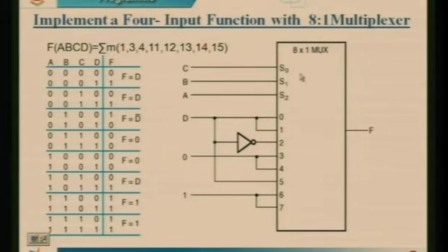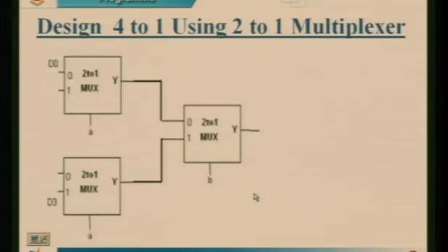So how will this multiplexer work now? If I give any of these combinations, I should get a single output out of here. Suppose I am giving the input 1, 1, 0, 1. So 1, 1, 0 means 1, 1, 0 here, right? And 1 will be here. So for 1, 1, 0, my output will be 1. So this particular line will be selected, that is I6. I6 is nothing but it has got logic 1. So this logic 1 will come here.